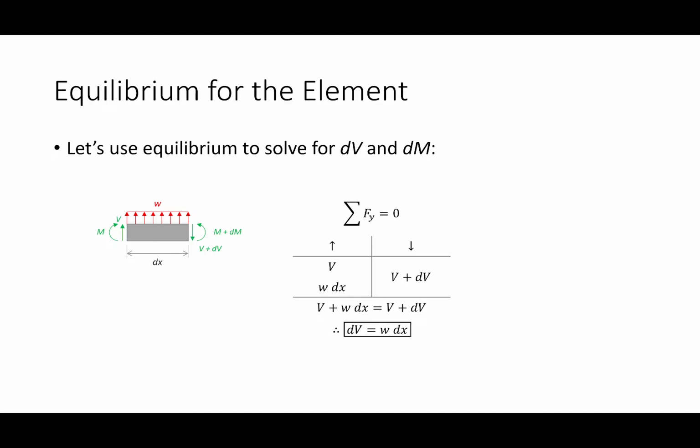Okay. What about this distributed load? Do I need to consider that? Okay. So it's going to go on the left side, and I'm going to have a force times a distance. What's the force and what's the distance? The force first. W dx, because it's the magnitude times the distance, right? It's like 2 kips per foot over a distance of 30 feet. So it's W dx. What's the moment arm? dx over 2. Does that make sense? Everybody okay with that?